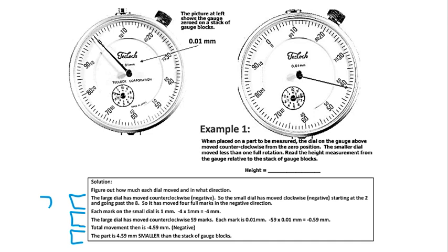So this is where we're zeroing out the gauge block. So we are counting all the revolutions. The second one is after you swap the object, and you will either get a plus or minus direction. You know, here in our case, we get a minus direction. So then you are going to subtract that from this, okay? So right now we're reading with the direction, so you don't really have to do the manual calculation.